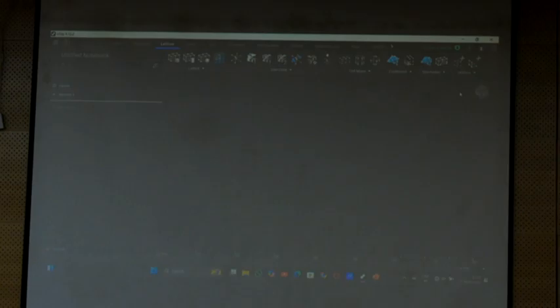And this is like an implicit body, it will take time. Suppose this is a laptop, and you are working on some high configuration system. The good thing about this software is that we can easily design a BCC lattice structure in SolidWorks, you might have found the videos also. But the problem with SolidWorks is that we design one unit cell and pattern it in 3 directions. We face this problem personally: since we are repeating, the system processing will be very slow, it may die also.